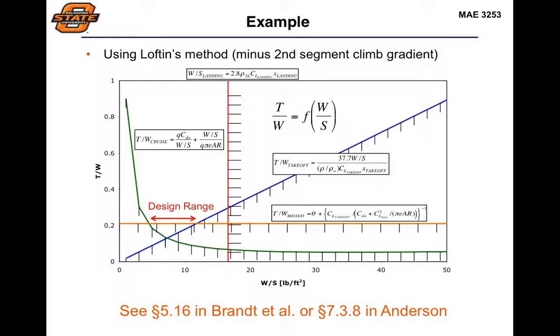So when you block all these out of bounds areas off, then what you're left with is this feasible design space. And so then you could say, well, any design that meets these requirements that fit within this particular range is going to be good. So it's going to meet our requirements that we have. And so you could say a design up here is just as valid as a design down here. But obviously what you end up with is a system that's going to be over-designed if you're way up here on the top side of the space that has a higher thrust-to-weight ratio in this case than a design down here would. So you'd obviously push yourself down to this lower design space.